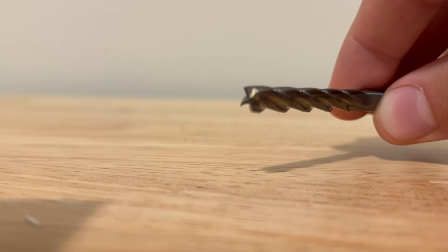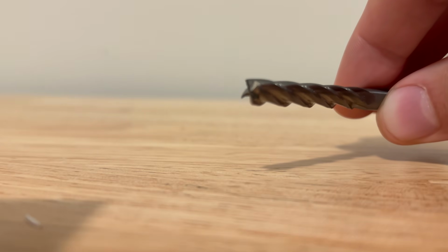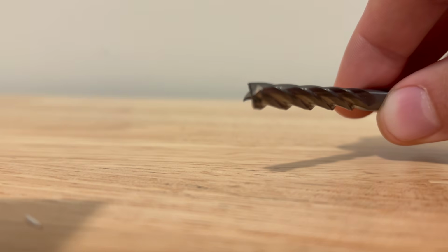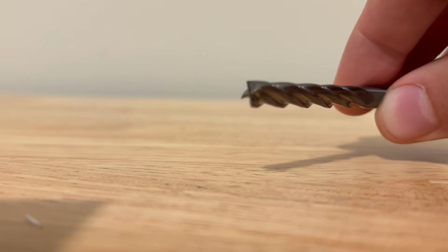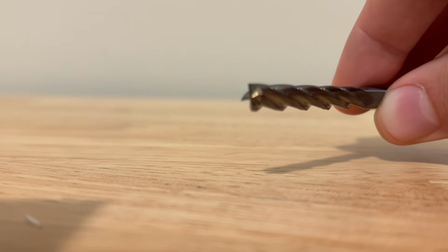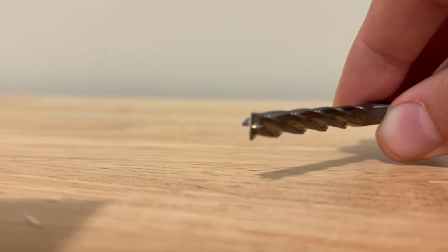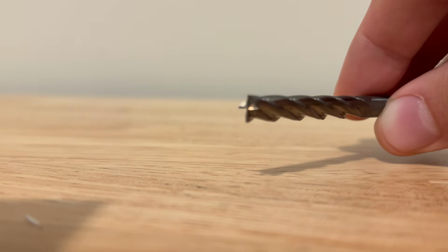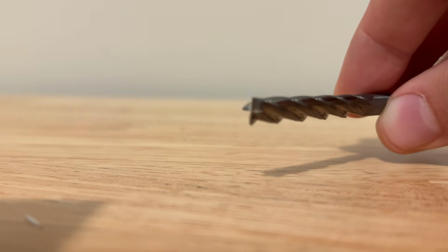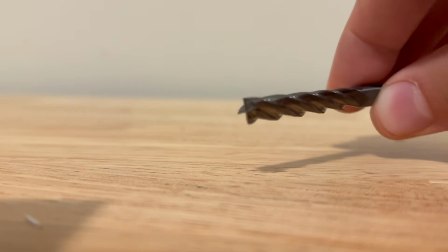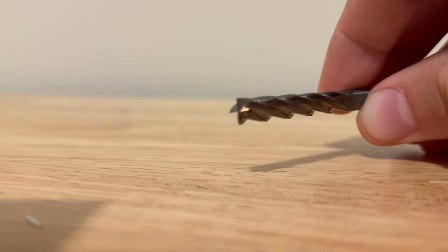But most of the time, you're going to use 3, 2, and 1 flute end mills of ball nose, flat nose, radius nose, all things like that. Stick to 3 and lower on flutes because in reality, aluminum's probably going to be the hardest material you're going to cut on these machines. So now that we went over flute geometry, let's actually go shop.